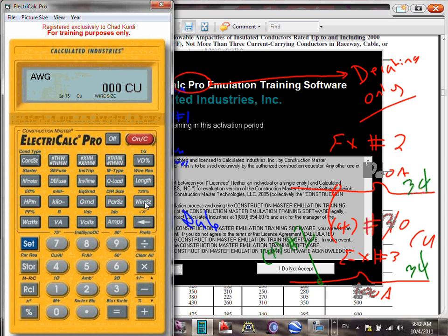Now the 100 amp might default you. Let's use the 100 amp. Now the 100 amp, remember, unless you know otherwise, it's going to default you to what? We size here based on 60. So I'm going to change my calculator to 60. Set your calculator to 60 and see if it sizes for you based on 60. Close it. So I defaulted it to 60. Everybody see I defaulted it to 60.